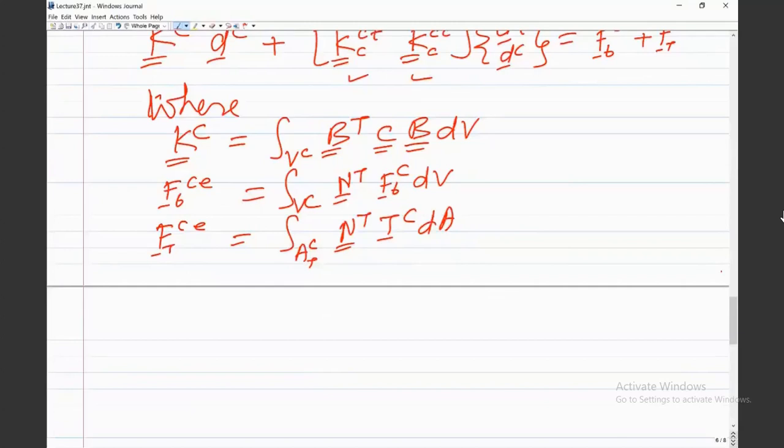In the software, you will have an option for the Lagrange approach, for penalty, and for the augmented Lagrange method, and there are a few more methods, but these are the most popular ones. I will just briefly tell you what is done in the augmented Lagrange method. We have discussed Lagrange multiplier and the penalty approach.